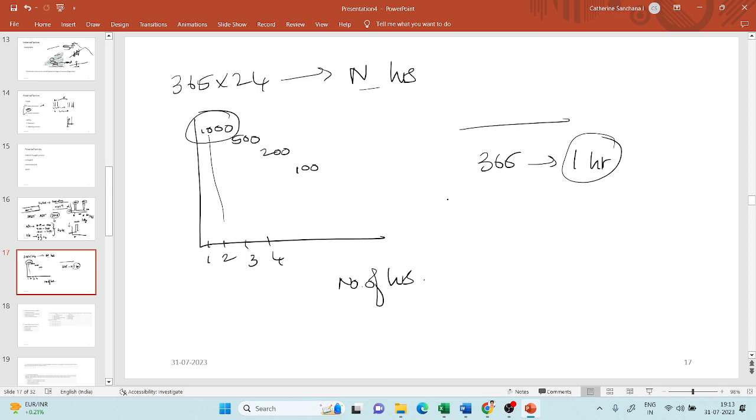So I'm going to come to a negotiation. I will say that I will leave the first 29 hours and I will pick the traffic correct. So 29 I will neglect. The 30th hour you take, and you take the traffic volume corresponding to the 30th hour. Okay, so this is what I will take for designing the road.